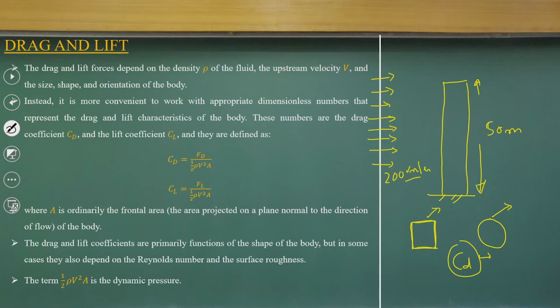So, we can look at this elementary geometry and understand which one will give the minimum CD values. It's not something you can say just graphically. That is the reason we conduct a series of experiments, and finally we provide the CD values, which are the guideline for an engineer to decide when constructing a high rise building.